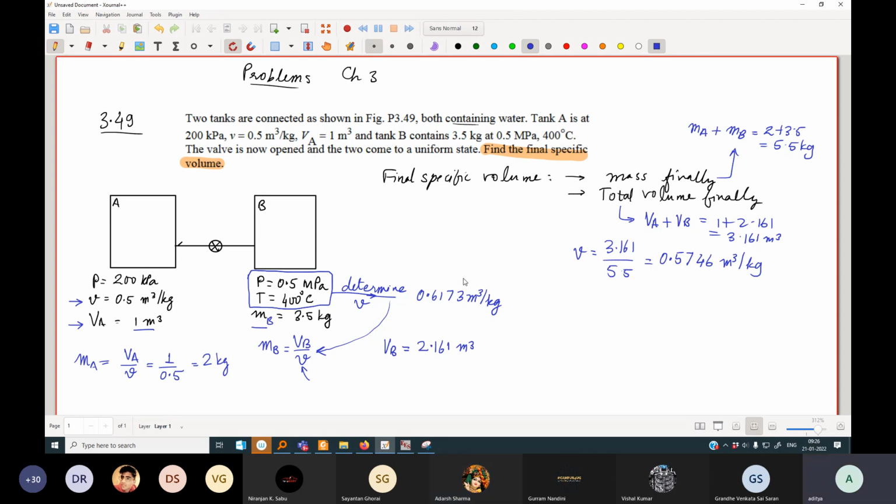If the problem is not ill-posed, there are two ways of going about it. First of all, they have given it in the problem, so you know that the problem setter will not give you such absurd initial conditions where the initial state itself is not known. So I know that this is going to be superheated vapor. But you don't need to take my word for it. What we will do is, at 0.5 megapascal, first query what the T saturation should be.